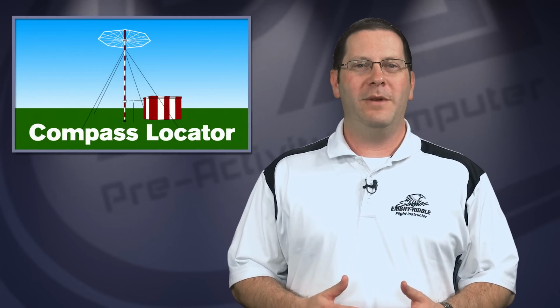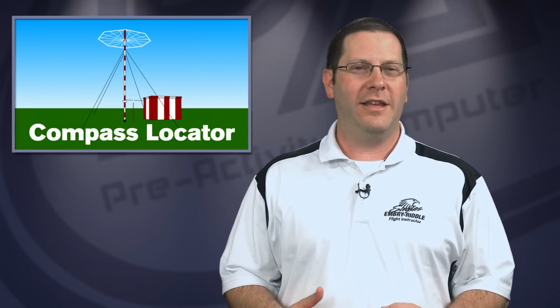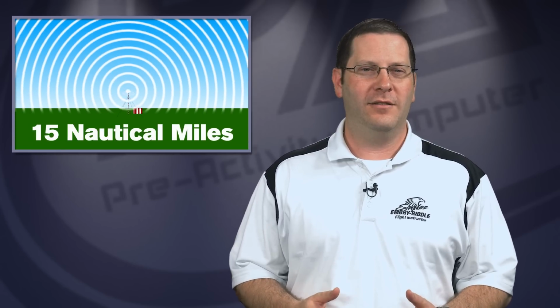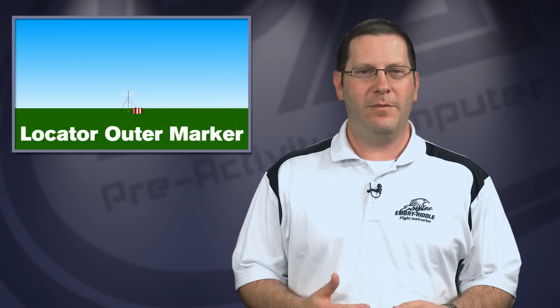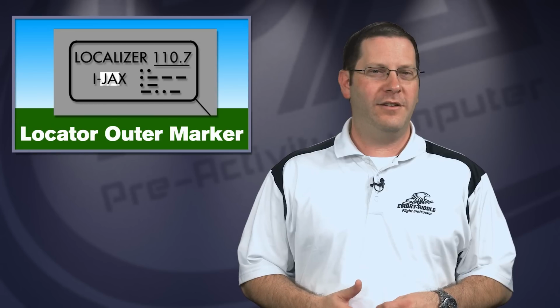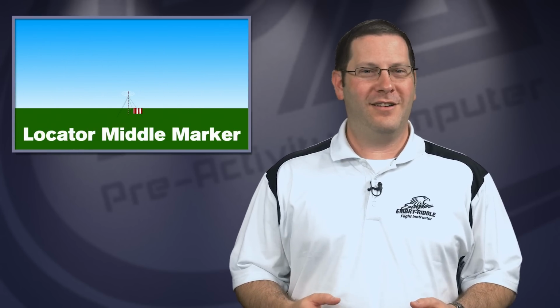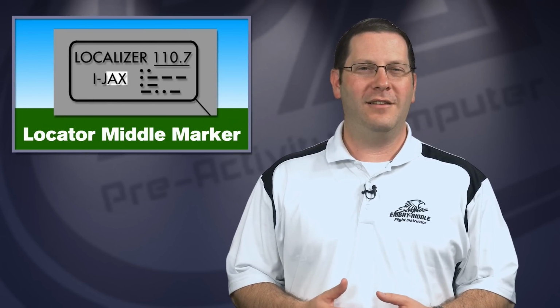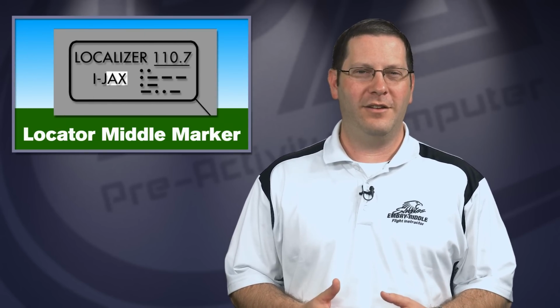On some approaches, there'll be a compass locator co-located with either the outer marker or middle marker beacons. These are low-powered NDBs that have a range of at least 15 nautical miles. Compass locators co-located in outer marker are called locator outer markers. These transmit the first 2 letters of the localizer identification group. Locator middle markers are compass locators that are co-located with middle markers. These transmit the last 2 letters of the localizer identification group.